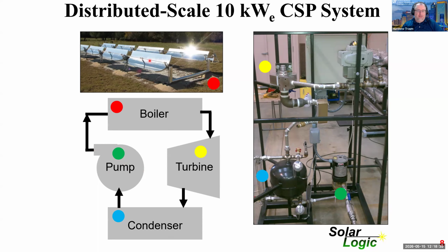It absorbed energy from these parabolic troughs, right? There's this little concentrator in the middle collecting sunlight. The fluid boiled, vaporized. It got run through a turbine. And then at the end, you guys remember from your Rankine cycle experience, you have to reject the entropy somehow, right? So they ran the now depleted working fluid through a condenser, recondensed it back to a liquid, and the cycle continues, right?